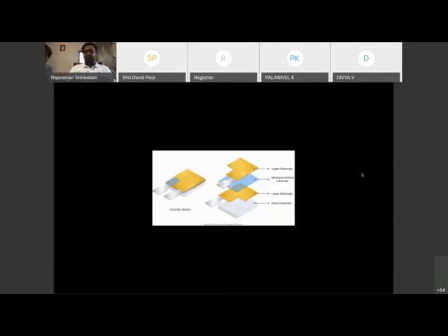So we can have a look at how it works. There are two electrodes, and there is a moisture holding substrate in the middle that is sandwiched between these two electrodes. This is the humidity sensor. When the humidity increases, there is a drop in resistance in the substrate that causes more current to flow through these electrodes. So that is how the humidity sensor works. More humidity, lesser resistance, so it will give out more current. That rate is calculated and converted into the humidity.